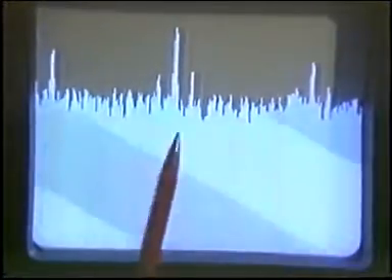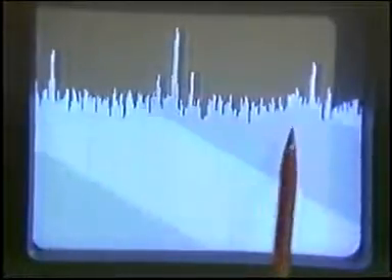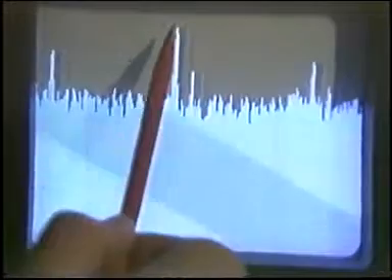This one, in fact, is the low frequency signal that Mike wants to recover. And this one is an interfering signal. And these are some of its components. And these are all distinct sine waves. The rest of this information here is in fact wideband noise. And I should just point out that the vertical scale is logarithmic. It's about 10 decibels per centimetre, so there's something like 10 decibels difference between that amplitude and the signal we want. So the interference is quite strong.